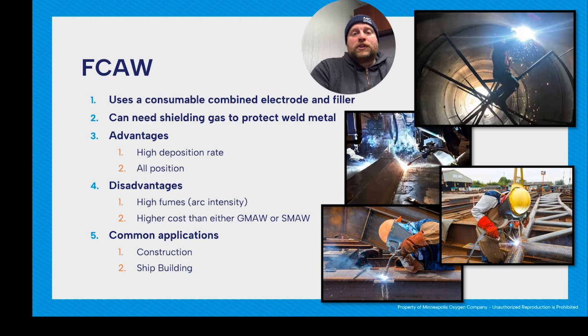You may need shielding gas to protect the weld metal depending on the type of flux core. So there's two types. There's the self-shielded, which works just like a stick weld where the shielding is provided by the flux. And then there's dual shield, where you're going to have the flux and a shielding gas. I love dual shield flux core because you can make really awesome welds that look great and are super clean, super high quality, things like that.